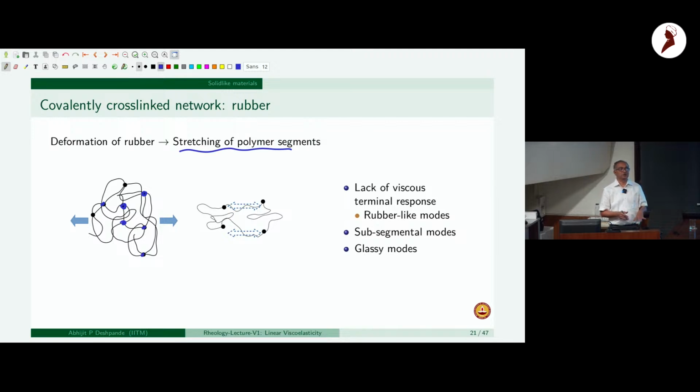If you go to very low temperature where you have basically taken it below its glass transition, again G prime is larger than G double prime. So you have both of these cases where energy storage dominates, and that's why we can use a rubber band basically where it's a perfectly elastic material. So dissipation is absent in the case of a rubber band kind of an application.